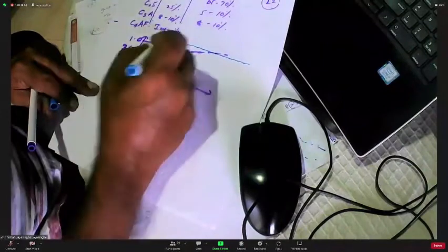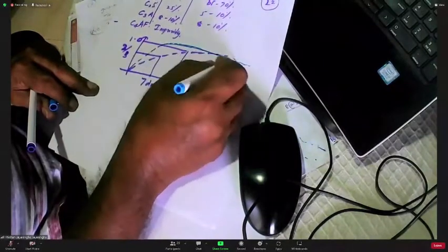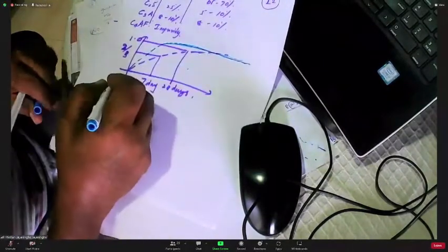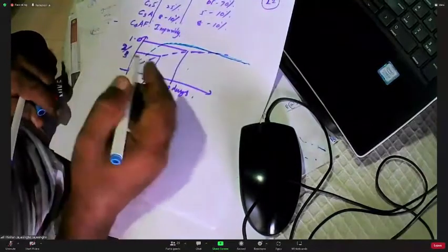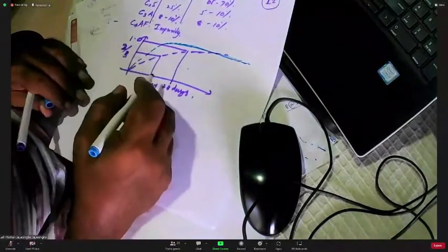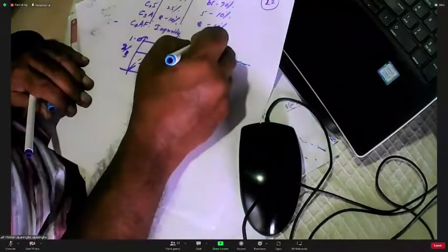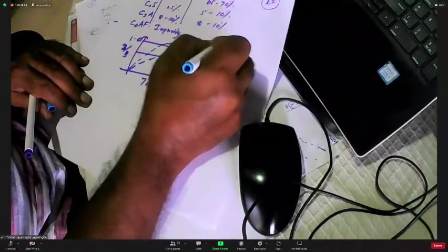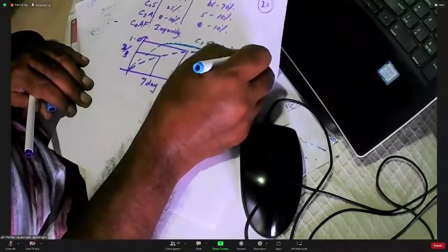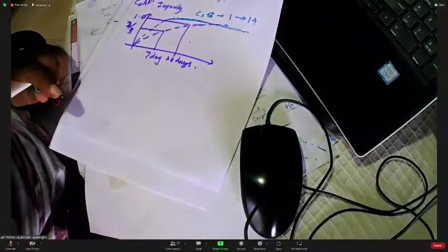Goes flat. Goes flat. Why? In 7 days, you get 28 days strength. Why? Lot of C3S. C3S is effective from 1 day to 14 days. After that, very little reaction. So you get very high strength early.